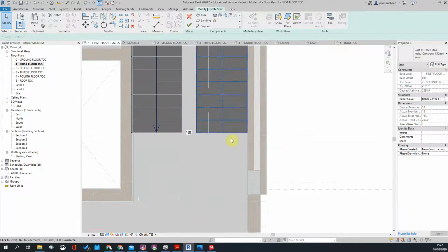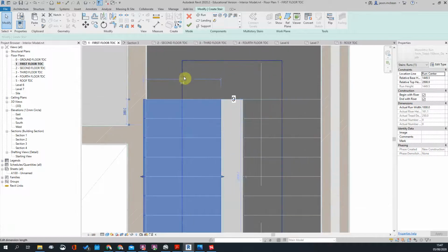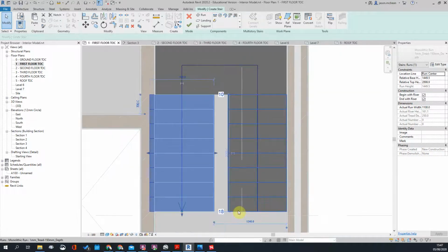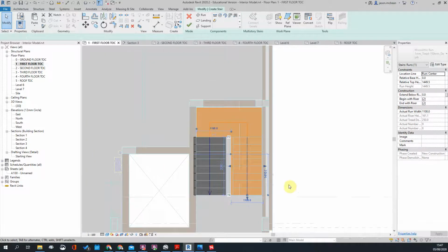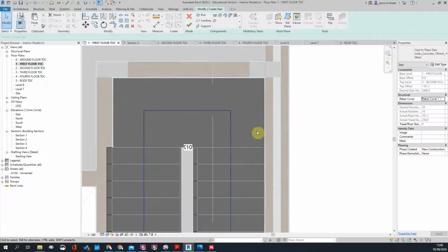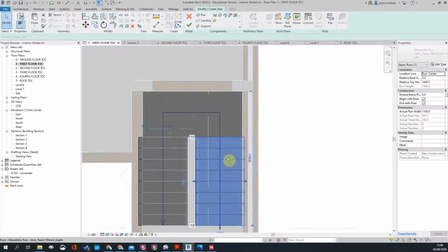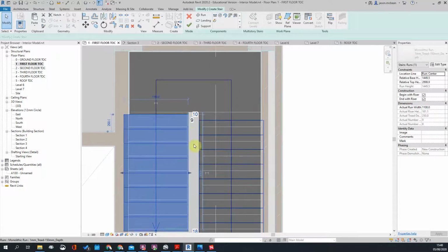Okay, all right. The reason why I'll explain what's going on now, but I can make this so let's make all of these 1100, because I need to copy the stair below. Generally, these follow the steps below. 1110. Remember, whatever your stair run is, your landing will have to be the same. Okay. All right, so that's fine. I'm going to move this away a bit. It'll adjust the landing. Likewise with this.